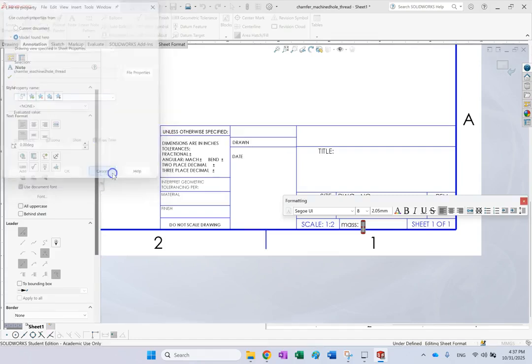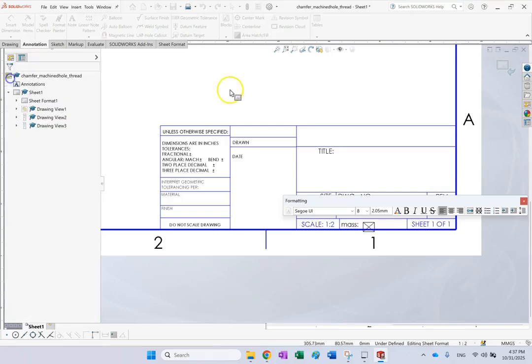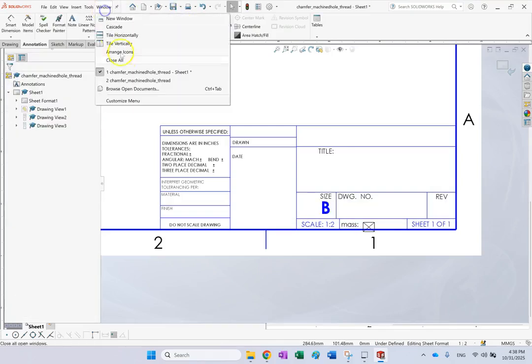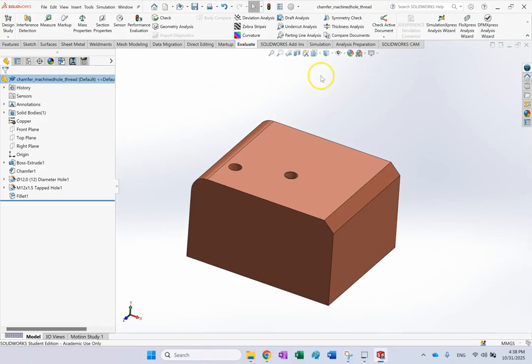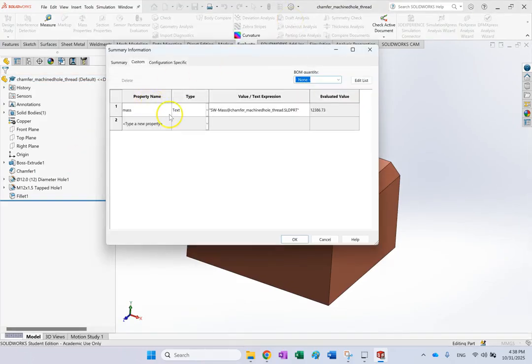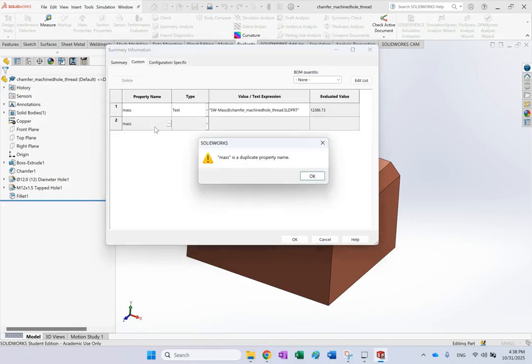And look what I did for this file. I made sure that the file has a mass property. So if you go back here, because by default your parts don't have a mass property, but look, when I went here, I created this mass property, right? So let me show you again here. So you go and say, hey, this is mass, and then you enter.